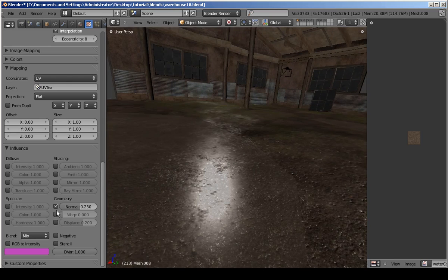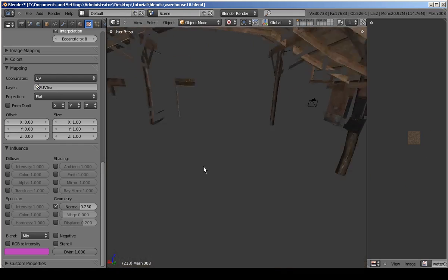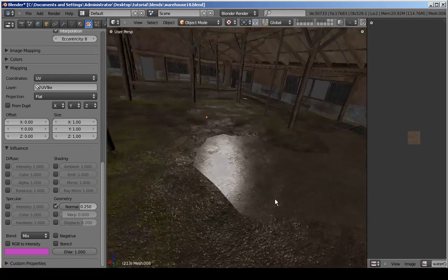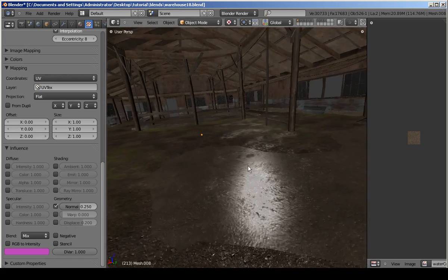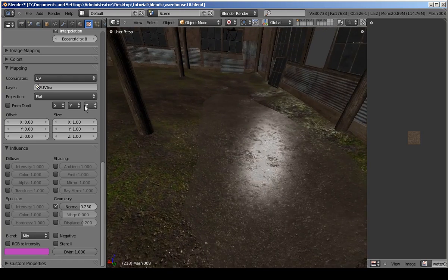Blender's really weird like that. To fix it, I end up deleting all the problem puddles and just duplicating the one puddle that works and moving it around the mesh. Really lame, and I don't know what kind of bug this was, but luckily it was an easy fix as soon as I figured out what to do.